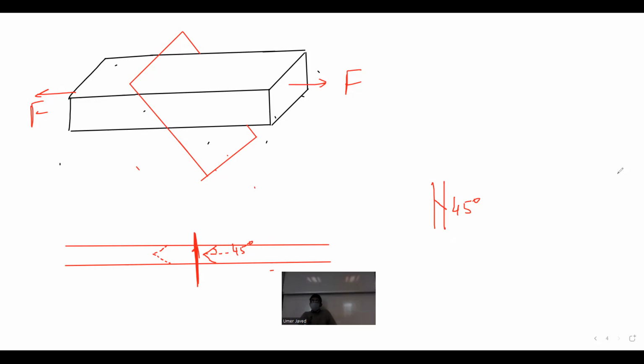If the resultant force is acting straight like this, then there is no point of the curved area. The right cancels with the left, and I took everything, and there is just one giant vector acting like this. So what exactly is sitting for that giant vector? There is just this projected area.